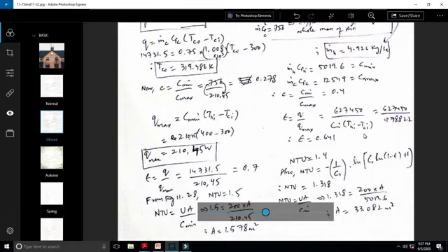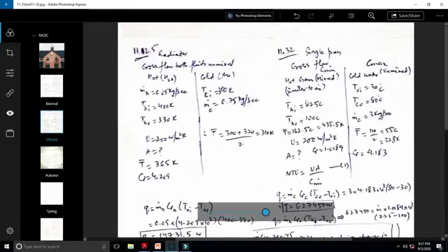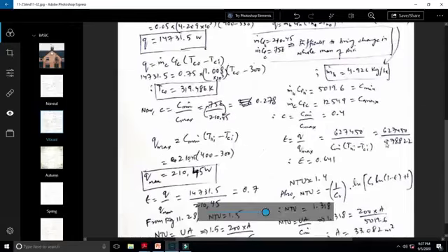So if we work things out, we would be able to calculate this Qmax as 9788 watts, because Cmin is 5019.6, and Th,i is given to us as 225 and Tc,i is given to us as 30. So if you put the values, we will get this value of Qmax, and the ratio of Q to Qmax will be 0.641.